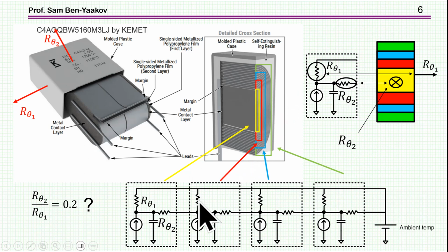It's not just one volume, but you have layers and layers. Obviously you can make too many of these, so you can break it down into some units. Each one will have its source for the power, the capacitance, heat capacitance, thermal resistance, and then we have the thermal resistance going all the way, as I have said, this way, and then also to the side.